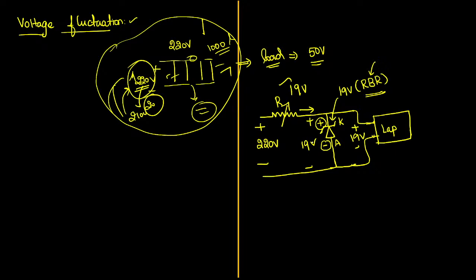So what will be happening here is, when we are receiving 19 voltage here, this Zener diode will turn on, and cathode will become positive, anode will be negative. That 19 voltage will be highlighted like this. Now, will this voltage be fixed or not? Yes, it is fixed, sir. So this 19 voltage is fixed.